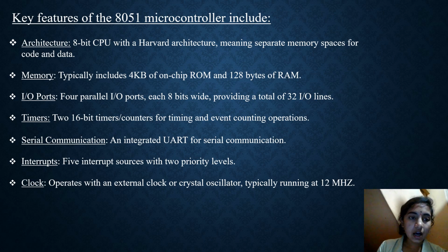So next is I/O ports. So there are four parallel I/O ports, each 8 bits wide, providing a total of 32 I/O lines. So next is timers. Two 16-bit timers or counters for timing and event counting operations. So next is serial communication, an integrated UART for serial communication.